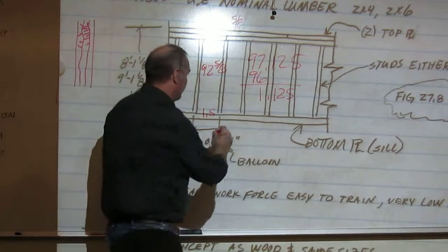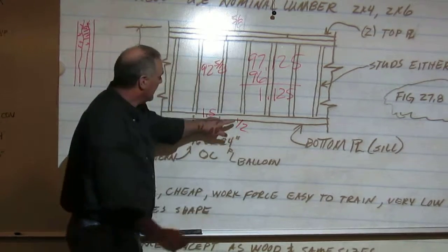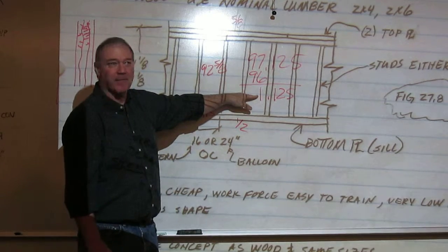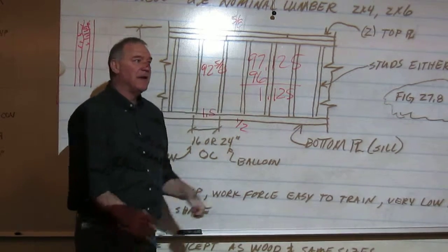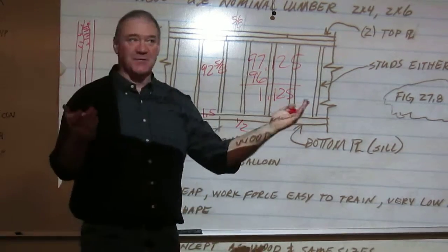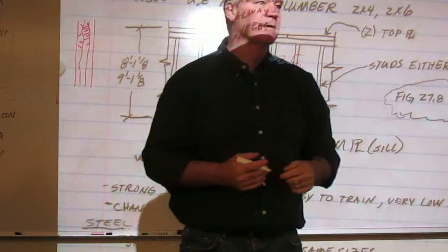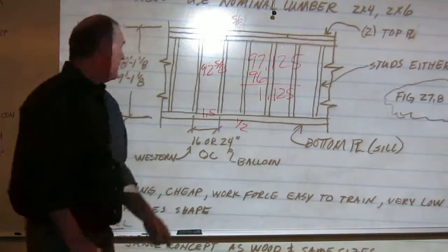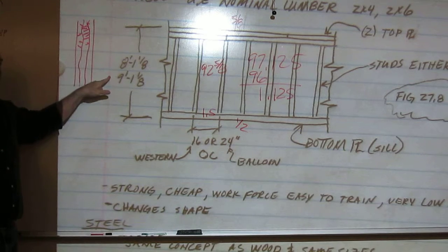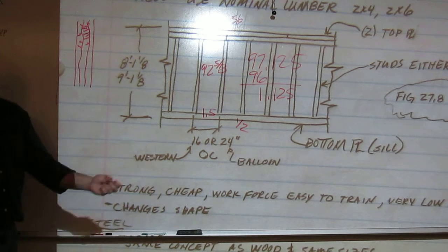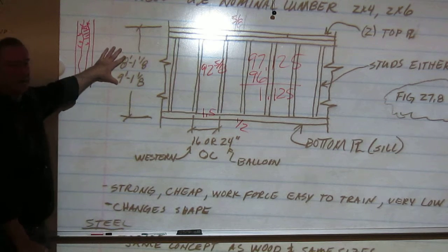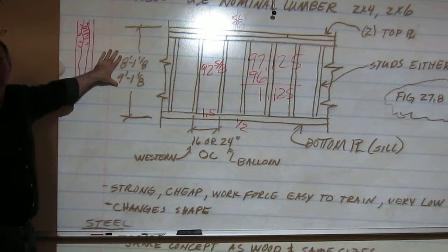Well, if you take a 1/2 inch and 5/8, that's equal to 1 inch and 1/8. So if I do an 8-foot wall, I got 8 foot clear once I'm in my finished space. A 9-foot wall does the exact same thing. I'll have 9 foot clear when I'm done, approximately, depending on what I put on the floor. So that's why we have these weird sizes of an actually built wall.